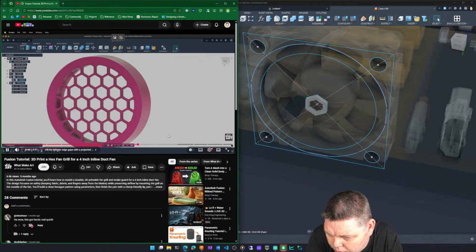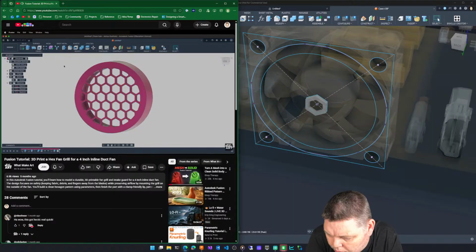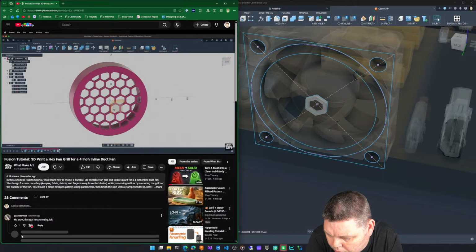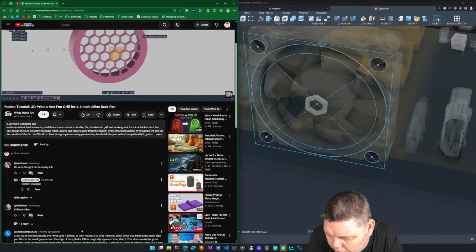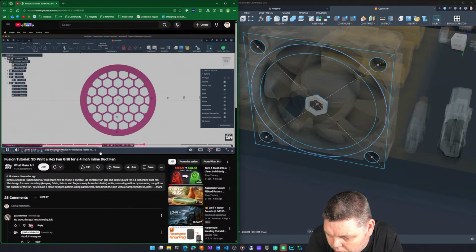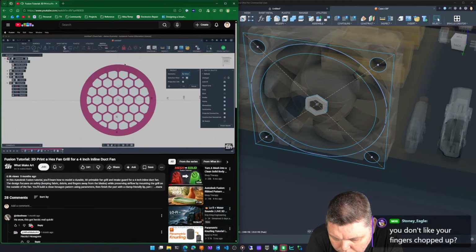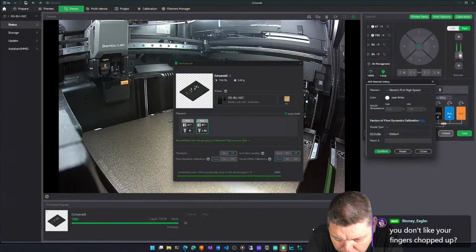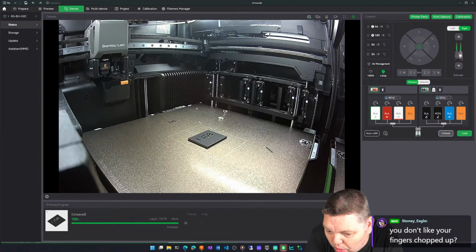Now I want to add a ring around the edge here so I can easily attach fabric tubes to the inflatable fan. So we'll create one more sketch. I can either create the sketch on the original plane or right on this face. I think this face is fine. Then use P to project. Don't think that worked.